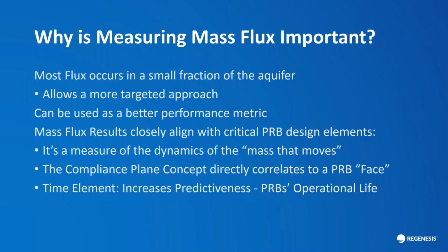Mass flux results closely align with critical PRB design elements. It's a measure of the dynamics of the mass that moves. The compliance plane that Paul talked about earlier directly correlates to a PRB's face. It's a very powerful concept. How much mass is the PRB seeing every day? And the time element, a little more subtle but a very important element, is that it allows us to make better predictions and do better remediation for operational life. We can estimate an operational life much more effectively if we have a time element.